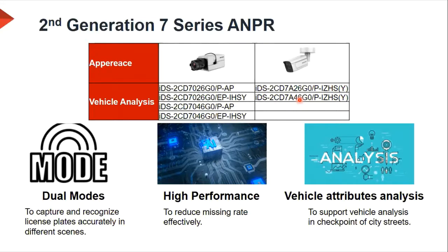Then the other thing for technical is to set it up within those distances, and also the height of these cameras. These 2 cameras you want to install at a minimum of 1.5 meters. Do not put them on the boom motor, the boom box that controls the boom, it is too low. It needs at least a 1.5 meter height, up to about 4.5 meters high. For these bullets, I wouldn't go higher than that, but between 1.5 and, let's call it, 3.5, 4, 4.5 meters should be good, but not higher than that, and nothing lower than 1.5 meters.